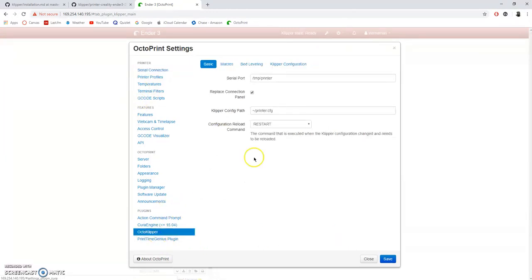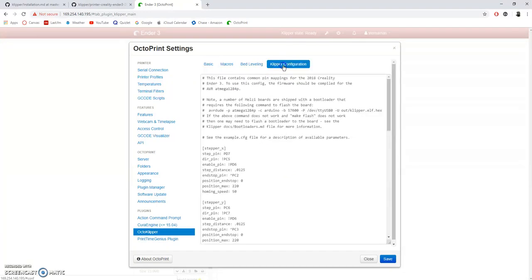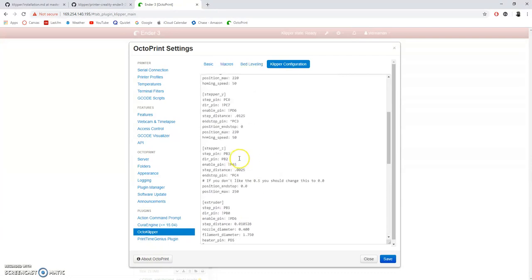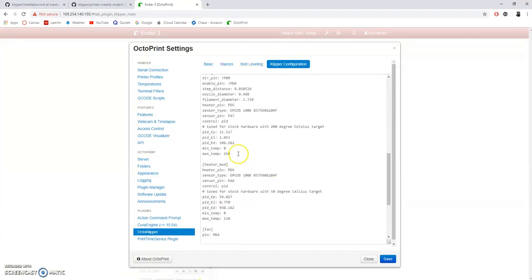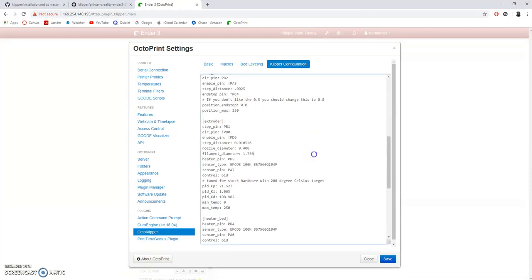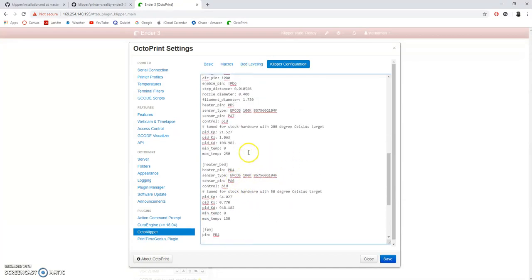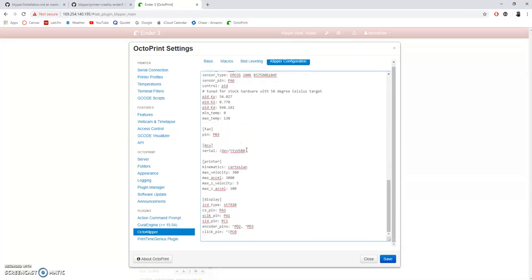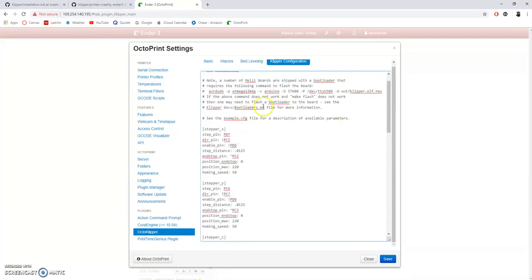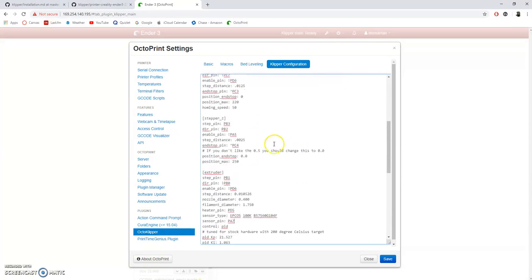it's there for you. Even the config file. This is why I said earlier that the SSH wasn't particularly user-friendly with upgrading that. All you can do is add in your settings in here. So for instance, if you want to add in your pressure advance settings for Klipper, you can do that right in here, along with your pressure advance look ahead, your square cornering velocity, those settings as well. And you can also lower the max acceleration, max velocity, that kind of thing, and change the pinouts if you have a custom bed leveling sensor. So in my case, I do not.